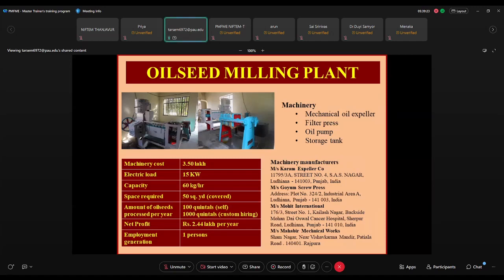The rice bran contains nearly 15% oil. But again, the problem is that we cannot use an expeller for rice bran oil. Rice bran oil has to be extracted by using the solvent extraction technique only, and it has to be employed at a very high level.